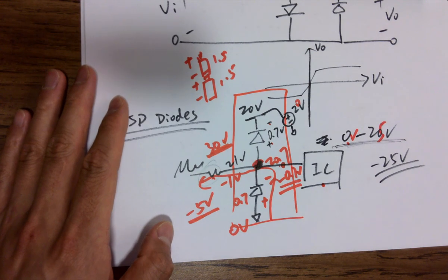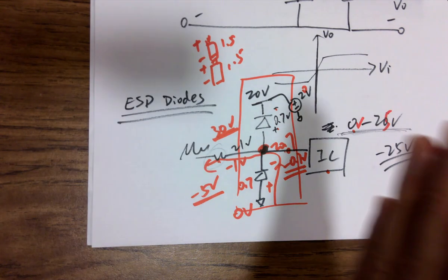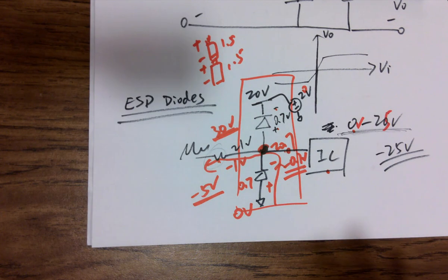And how to design the diode? I mean, for schematics, it's very simple. Just 2 symbols, put them together, right? But for layouts, there are a lot of considerations and requirements. And that's the IP of TSMC. You won't be able to see it. You can only see the pads, but not the details of the layout inside the pads. But you do need to know that there are ESD diodes in the pads, for sure. Okay, keep that in mind.